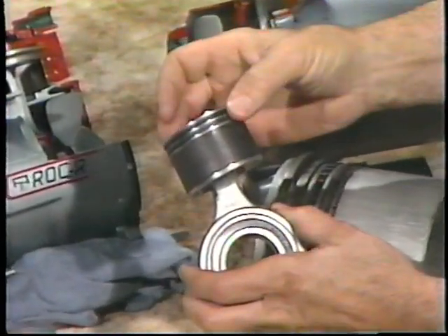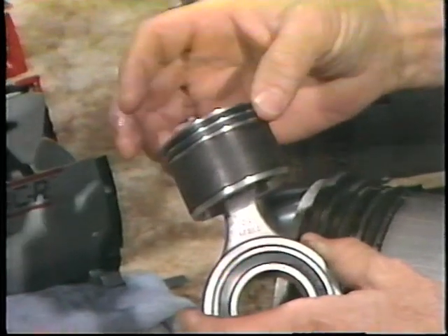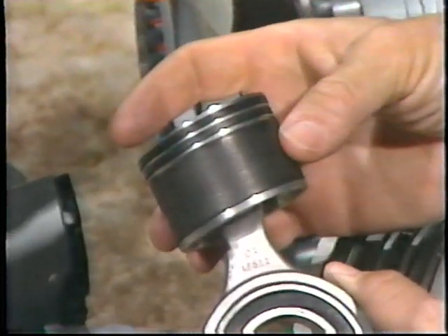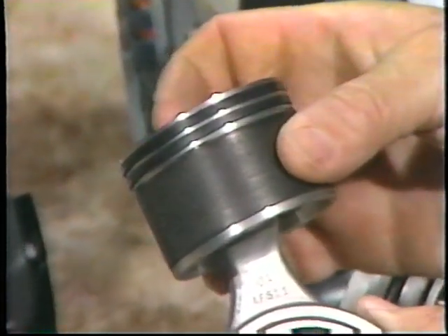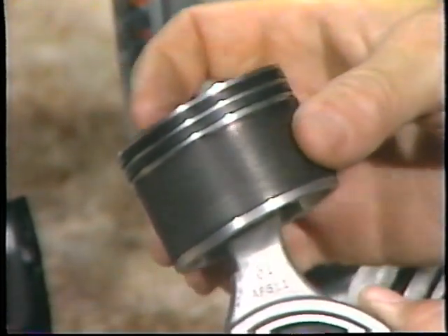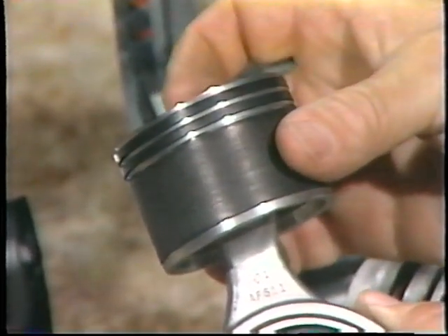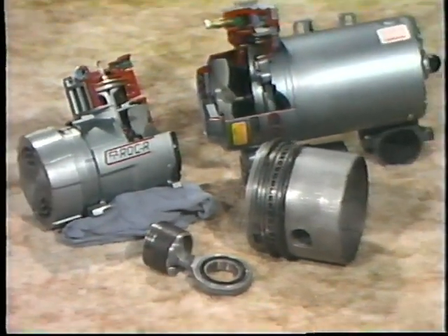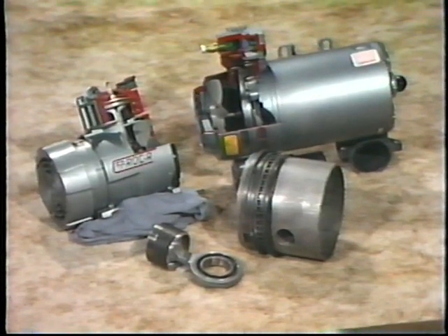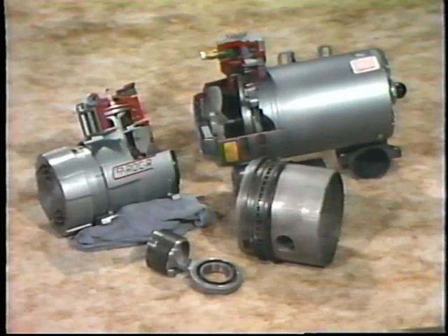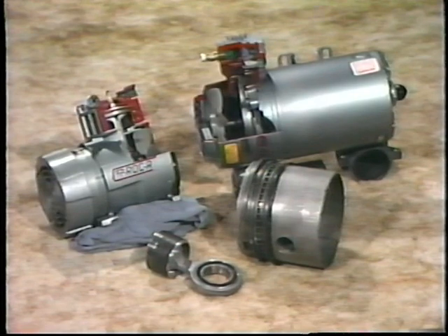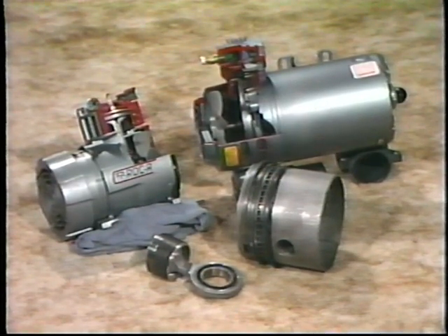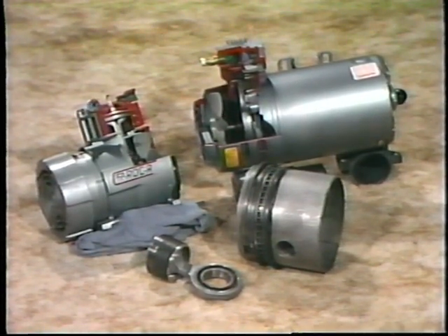This piston is used on a compressor which requires no lubrication. Some of these pistons have piston rings like this, and this kind of seal, which is called a skirt. The rings, or skirts, are made from low-friction materials like graphite or Teflon. While non-lubricated compressors have a definite place in industry, you should know that they are less efficient and subject to higher maintenance cost than lubricated units.